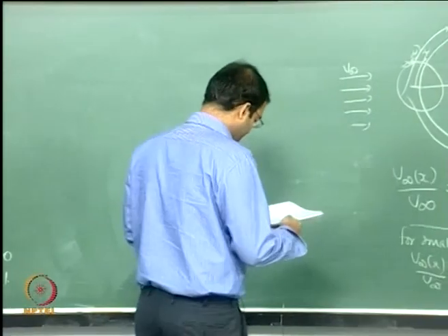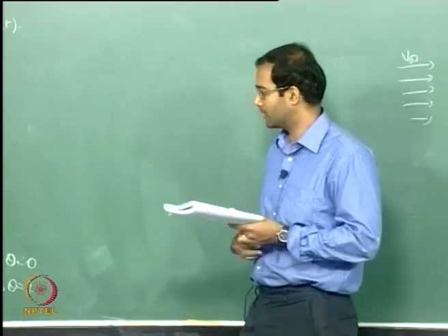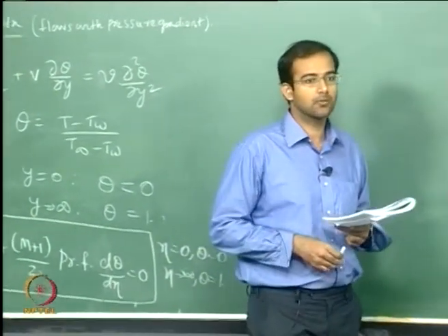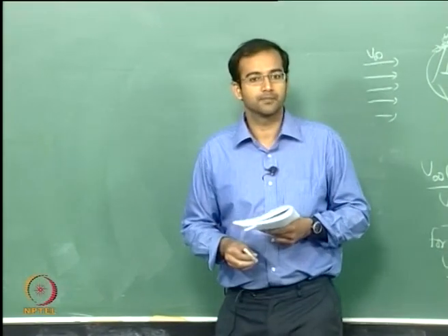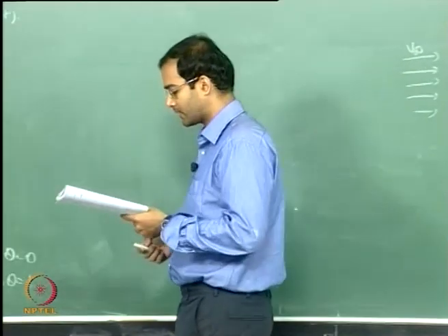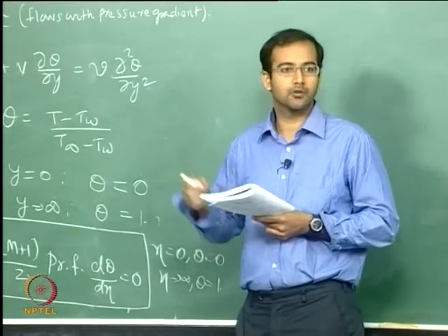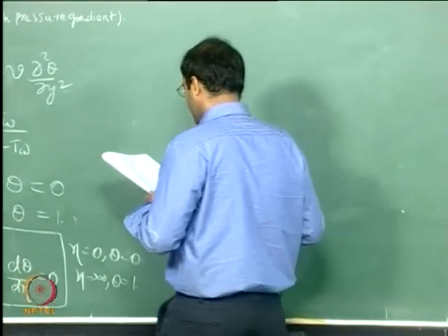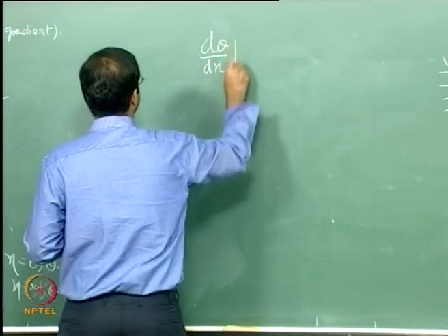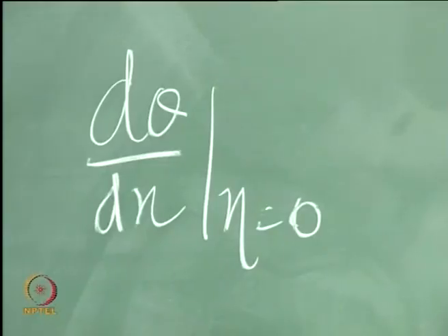Now what I am going to give is just the way we tabulated the curvature at the wall for the velocity profiles. Once you substitute and get the values, you can get the slope of the temperature at the wall for different values of m, for different configurations. How does it look? Because this is required to calculate the Nusselt number. Nusselt number depends upon this temperature slope at the wall. So if you do the tabulation, d theta by d eta at eta equal to 0, and m,